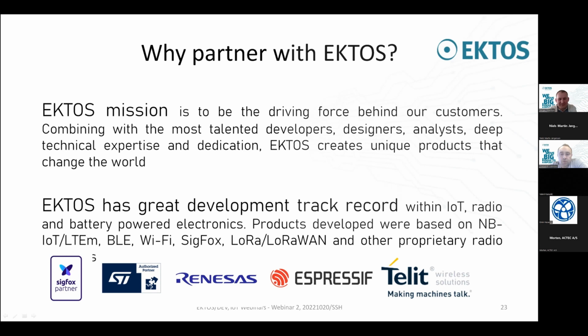Well, I think that the biggest benefit of Bluetooth will be the flexibility. You can do a lot of stuff. You can do firmware updates. You can do bidirectional data transmission and stuff like that. Where the old-fashioned IR is definitely a very simple way of transferring data between remote and the unit. But with the great small system on chip Bluetooth modules, price-wise we'd probably be looking at more or less the same cost as IR plus some processor. If you can combine the processing unit with the Bluetooth SoC, it might actually be comparable to the IR, and then a few passive components around an MCU and stuff. So that would be my interpretation.